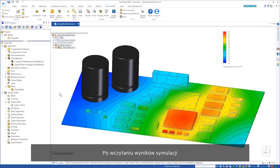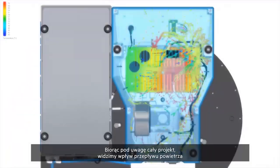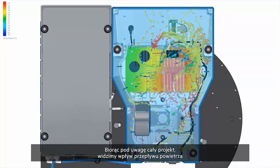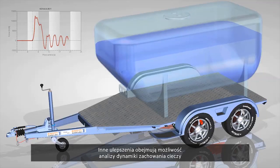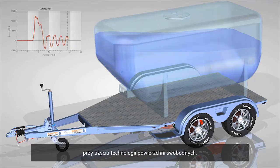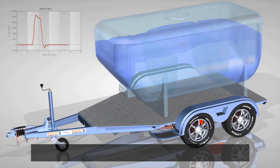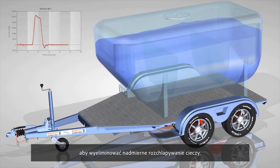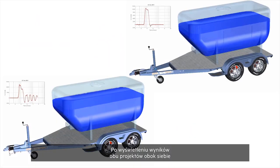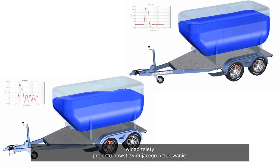Loading the simulation results clearly shows the temperature distributions on the board and components. Focusing on the complete design, we can see the effects on the airflow in that part of the assembly. Other new enhancements include the ability to analyze the behavior of fluids moving, sloshing, or pouring using free surface technology, as can be seen here when this trailer comes to an abrupt stop. Compare this behavior to a design that contains baffling in the tank to try and eliminate the excessive sloshing. Viewing the results of the two designs side by side illustrates the benefits of the baffled design.